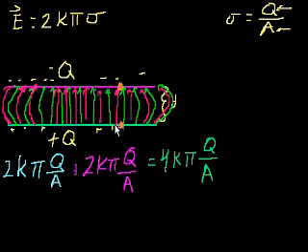The voltage is a measure of if any charge is here, how badly does it want to move to this point. So if it has a way to move. If we have air here, or if we have a vacuum here, it might be difficult or impossible for it to move up here. But maybe if we were to connect a wire where the charges could freely conduct, then it will move, and the voltage is kind of how badly does it want to move. You can almost view it as electrical pressure.